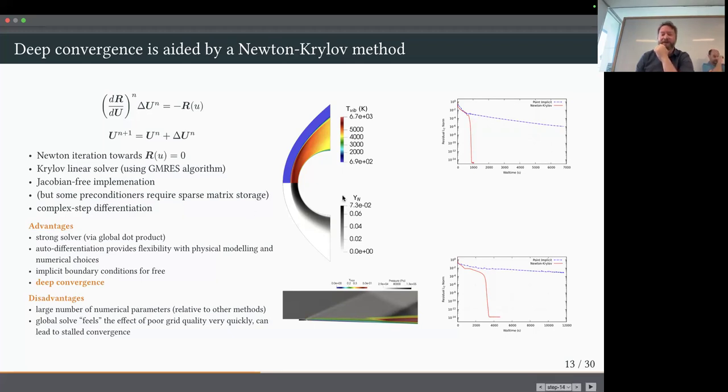So we presented this Krylov work at the AIAA conference a couple of years back, and my little postage stamp images here. We wanted to show that it was useful in this hypersonic context. This is a cylinder. It's a 2-temperature flow, so that's what I'm showing here, the vibrational temperature. And on the right is wall clock time to convergence using the Newton-Krylov method as compared to point implicit. Point implicit might be a little unfair. There's probably better methods, but I didn't have time to kind of implement every other method that could live in between this space. And just to show it works in another context, we also looked at a hydrogen combustion test.